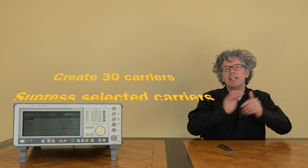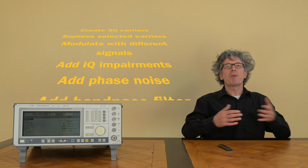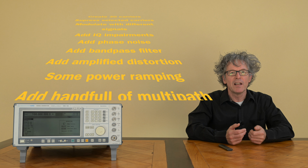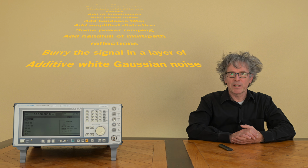For example, creating proper signals according to standards like GSM, 3G or GPS, creating real vector and IQ signals without additional equipment, but also creating a multi-carrier signal of, say, 30 carriers, then leaving some specific carriers out because there's going to be interference at those frequencies, modulating all these carriers with different content, adding some IQ impairments, phase noise, a bandpass, some amplifier distortion, power ramping, then adding a couple of multipath reflections that you define, and finally adding noise to it according to specified parameters.